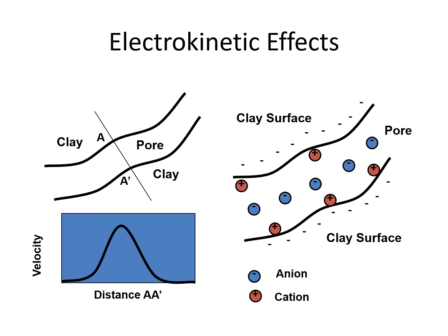The positive ones will be much nearer to the clay so that they can interact, unless they have already dissolved in the water. These are the anions and these are the cations, available in our channels. They play a role in getting retained or getting dissolved. Both are the cases. If we have a clay layer here, it will obviously attract the positive particles on the sides of the channel.